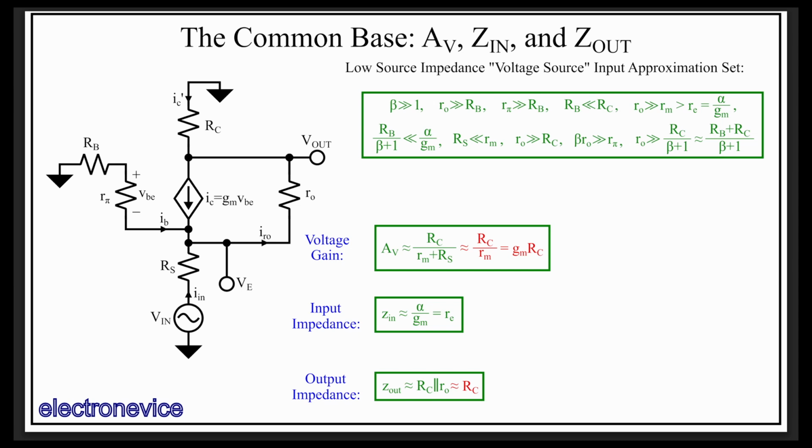Current sources have high source impedance. In the ideal case, this source impedance is infinite. However, as with voltage sources from sensors and other real devices, current sources similarly do not have ideal properties. And so their source impedances are high, but we don't want to have to rely on them being too high. Fortunately, the first approximation we need to make is that the source impedance is much greater than Rm, and since Rm is generally pretty small, this approximation does not seem to be much of a stretch for most real-world current sources.